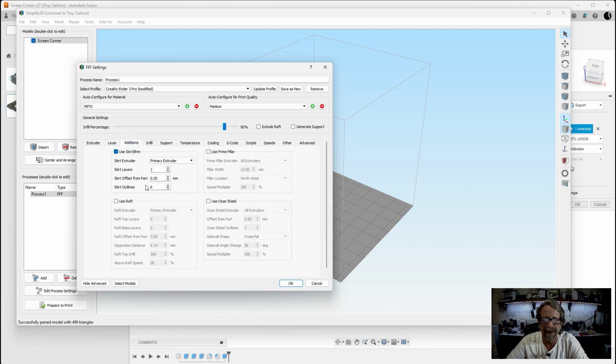Additions, we did, because it's PETG and it doesn't have a lot of flat spots on the bottom. It's got some good surface area, but this is all chamfered in. So you lose adhesion to the bed as your spaces get smaller. So I went ahead and added 6 skirts, and this one is on it. It is not separated.